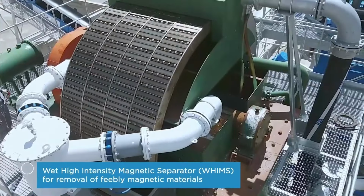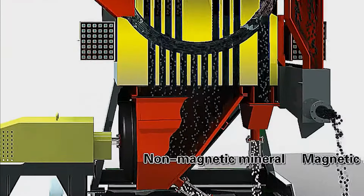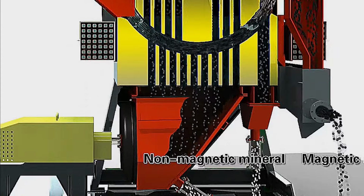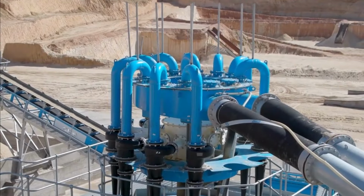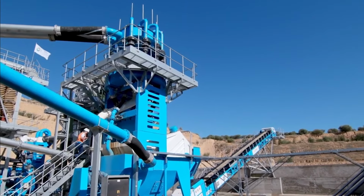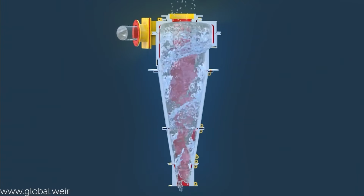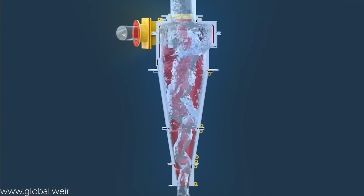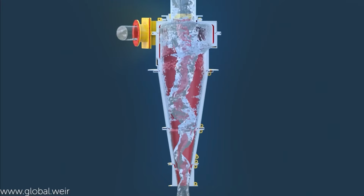Next, the wet, high-intensity magnetic separators separate silica from ferromagnetic materials by attracting them with their magnetic fields. The feed next enters the hydrocyclone, where centrifugal forces drive heavier substances out, leaving concentrated particles behind. The vortex finder causes a swirling motion, and fluid exits at the overflow, while solids exit at the bottom.